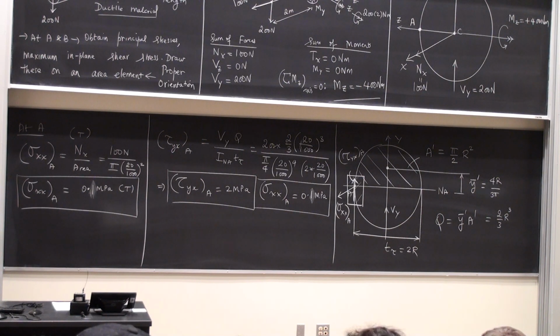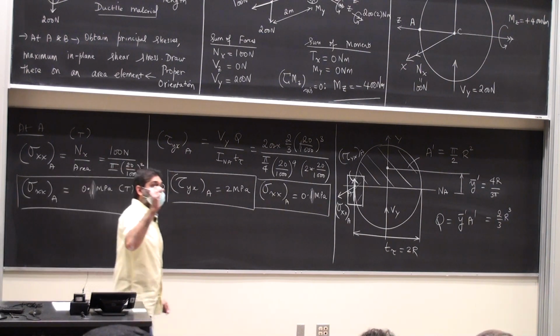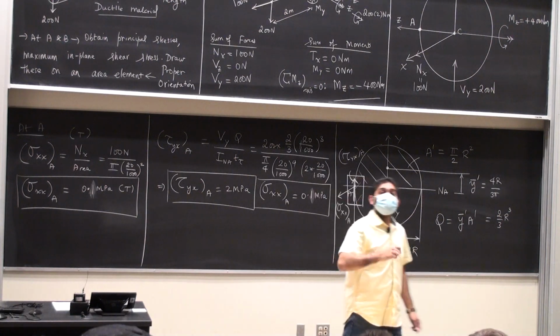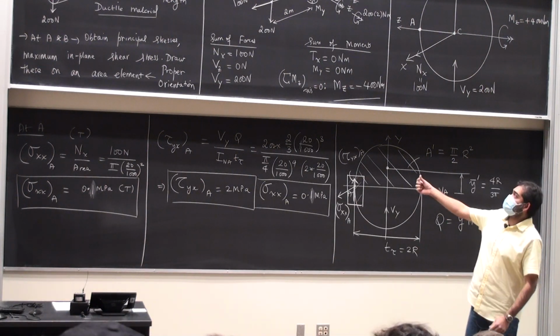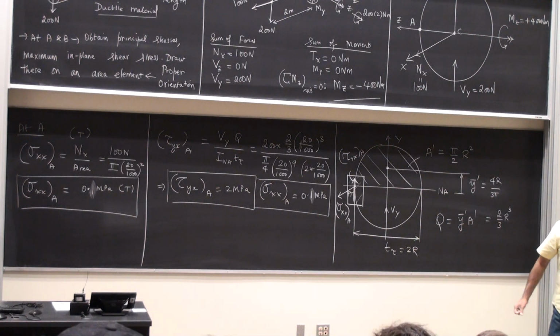And then draw the volume element. And then using the volume element, we will impose upon a plane state of stress, sketch out the Mohr circle, compute the principal stresses, which tells you that each and every point on the body will have an associated principal stress. Point A will have one, point B will have one, point C will have one, some other random point will have another one.